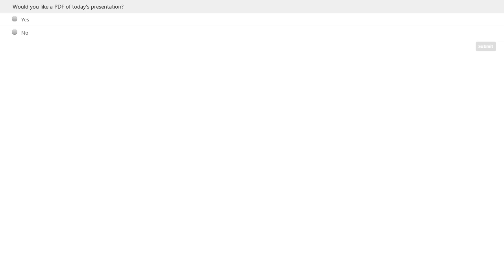First question: can PMTs and SiPMs operate in the IR region? So the response of SiPMs is limited by silicon. The current family of SiPMs has sensitivity up to about 900 nanometers, which is near infrared.